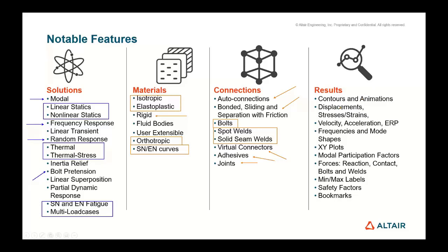Now, last but not least, in terms of the results, like we said, if you're conducting, let's say, a modal analysis in this aspect, what you will find is that you always get the same set of results from it. So you always get your frequencies and mode shapes, and you always get the modal participation factors from it. Say if I wanted to look at a linear static analysis, from there I'll always get my displacements and strains and stresses, and I can always get them in the form of XY plots.